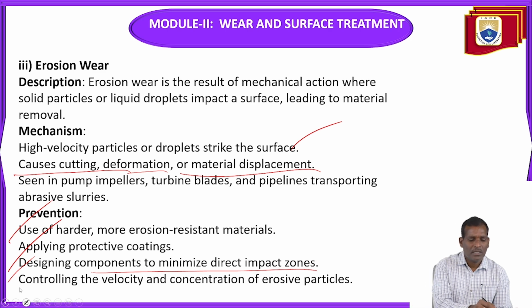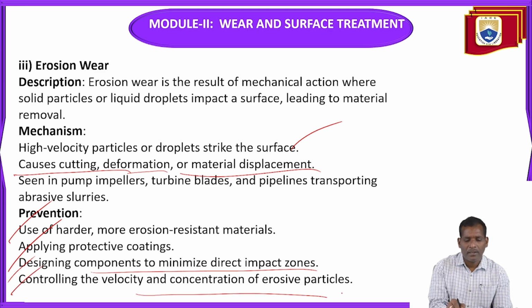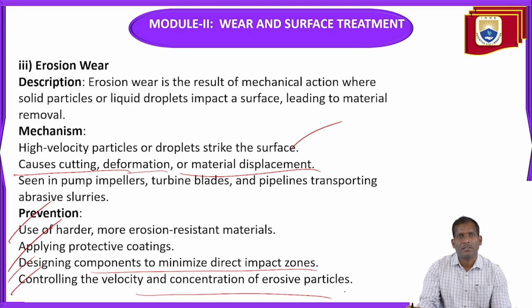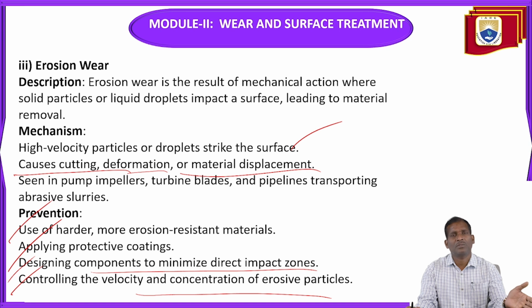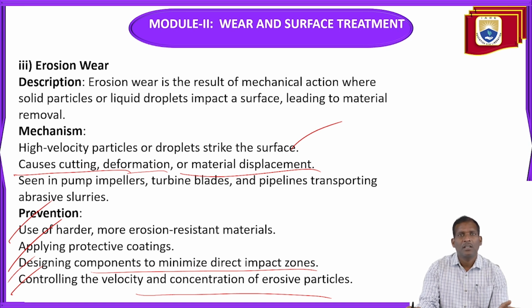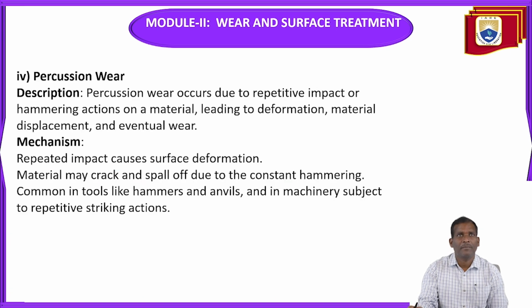Controlling the velocity and concentration of erosive particles. You can minimize the impacting velocity, and also the concentration of erosive particles, that is, which particles are impacting on the surface. So by using these methods, you can prevent this type of wear.